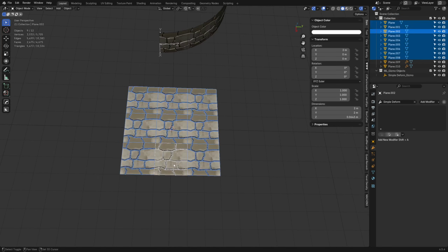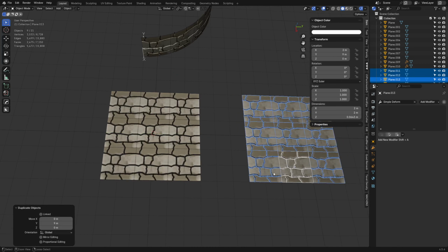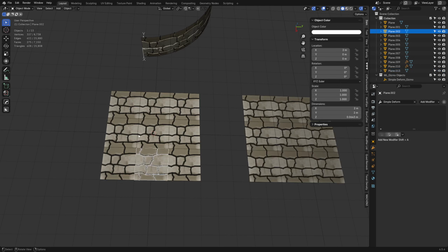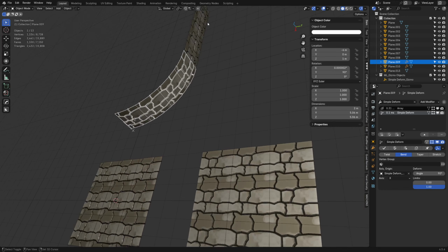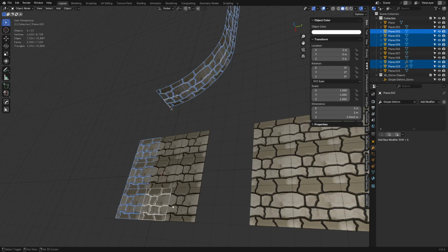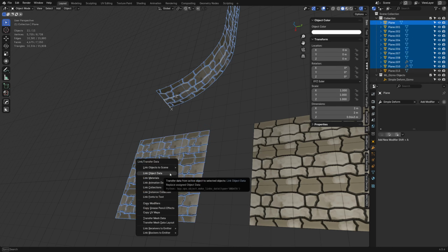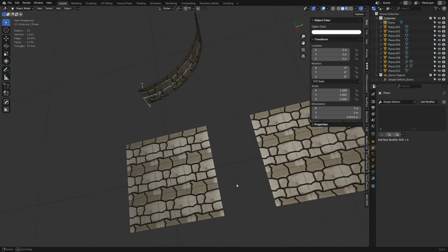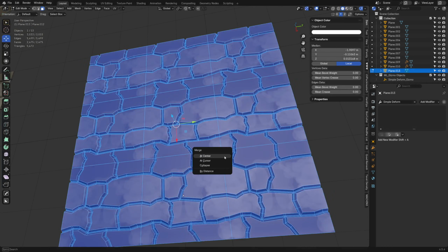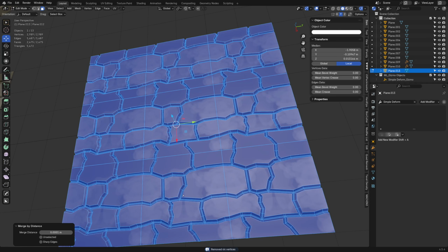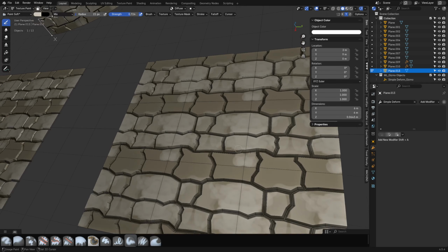But I want to take all of this. We can duplicate it out, maybe. Control J that and join it. That way we can make all of these instances again of the center one. Control L, link object data, how you update an instance, or a link duplicate. But this one here, if we press AM, merge by distance, set that to a really low value, it all merges together. We should still be able to texture paint this, right?